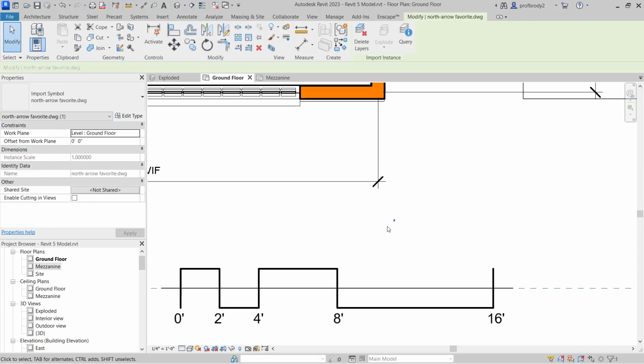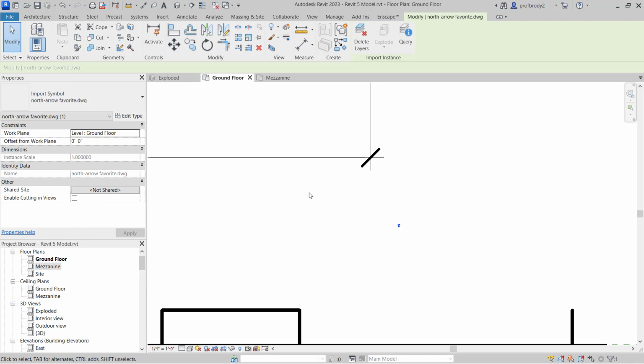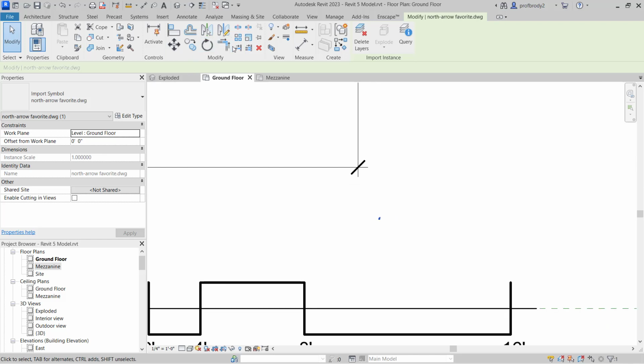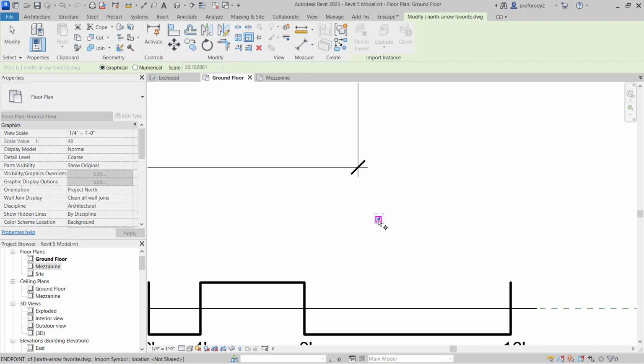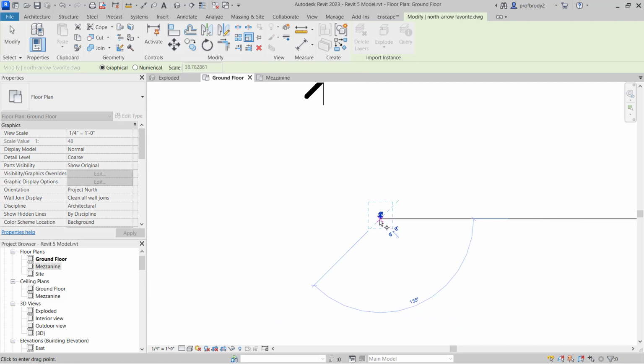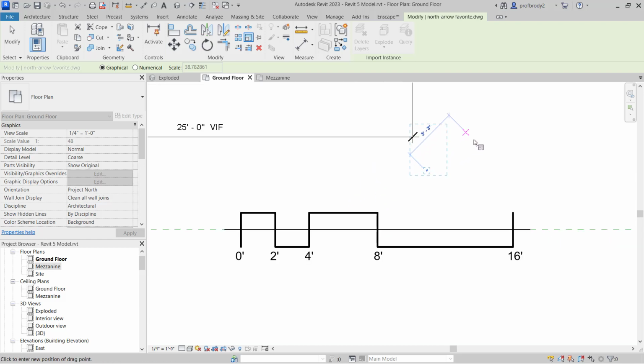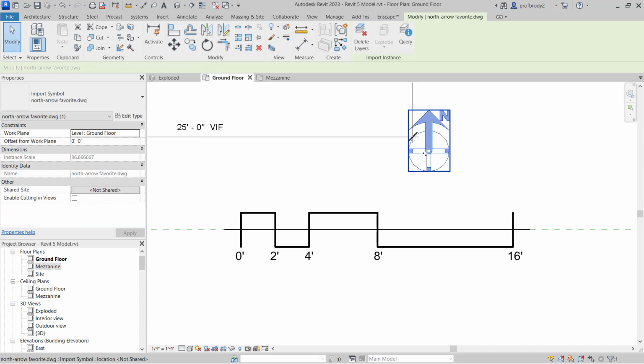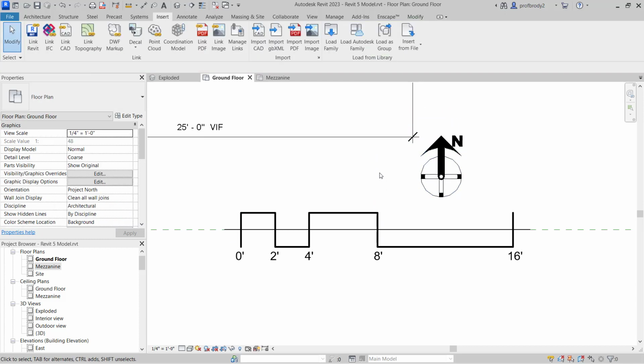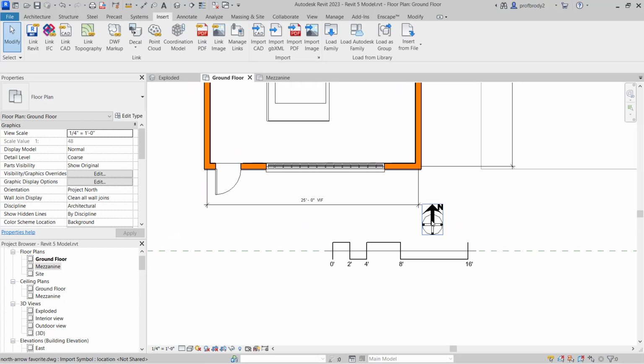Oh, it's so cute. And the reason is because it's probably like 2 inches in the original AutoCAD file. You can, with it selected, go onto the Modify tool. You see how it actually says north facing arrow or north arrow. And then you can use your editing tools. I can just scale it. When you scale, you click one point to provide a base point, another point as a kind of reference line. And then as you move your cursor out, you can see it will resize the object based on your clicking. And there you go, you have a nice north arrow.